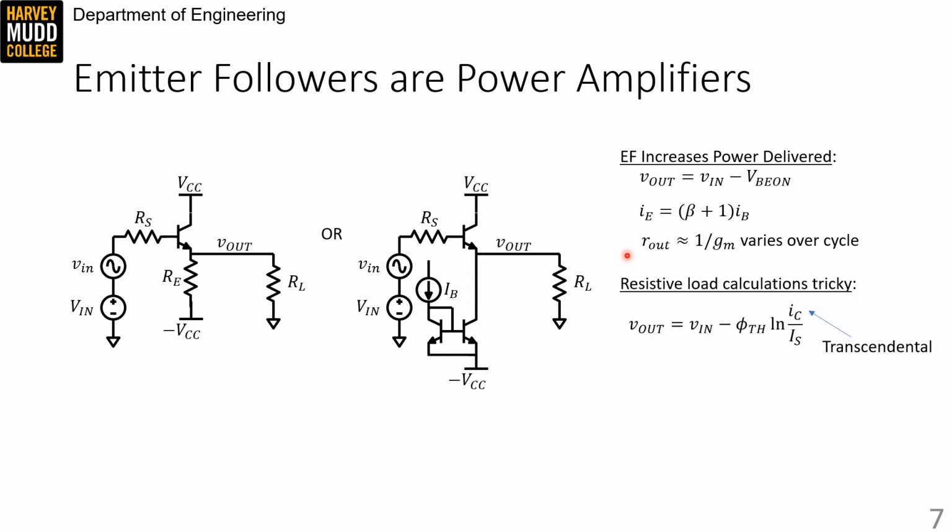The resistively biased emitter follower is relatively unpopular because it's tough to analyze, and as a result, tough to design. You'll see something that looks like this circuit in a lot of places, notably in voltage regulators, where the value of Vout is controlled by feedback. Voltage regulators, by the way, are also cute because they just replace RE with an open circuit and use RL as the DC path to ground for our power device.